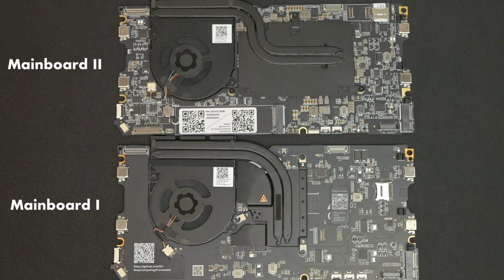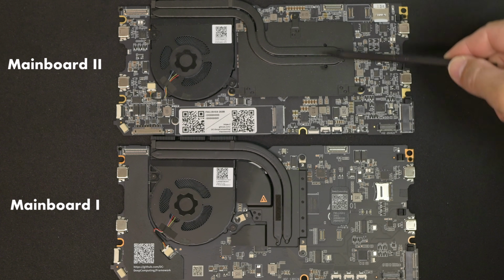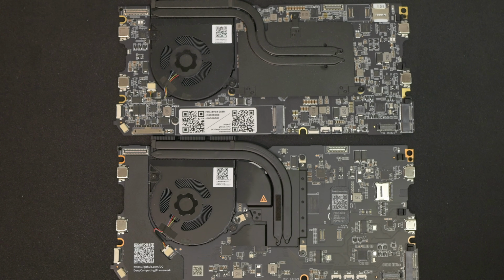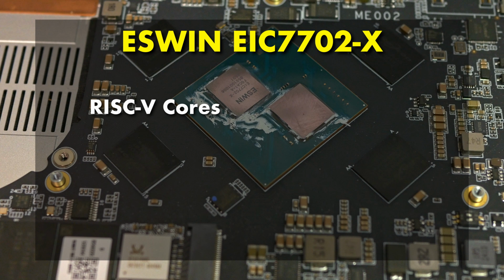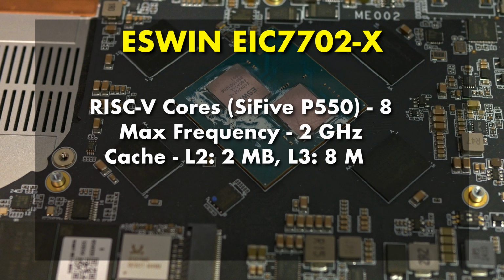Out of the box, you'll spot some immediate differences from the original. First, the heatsink has been redesigned. It's larger with a broader heat spreader to cool the beefed up SoC underneath. The chip powering the Mainboard 2 is the ESWIN EIC7702X, which Deep Computing lists as a RISC-V 64-bit 8-core up to 2 GHz processor. And those 8 cores are based on SiFive's Performance P550, a proper out-of-order Linux-class 64-bit RISC-V core.